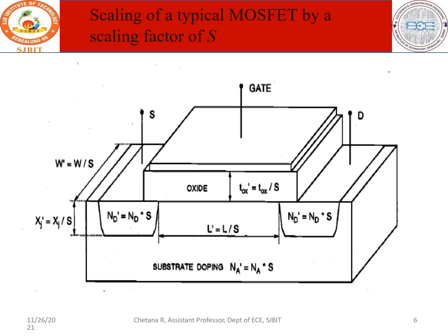Now how do we associate it with scaling? Whenever you are talking about doping, doping is normally indicated as Na, the ionic concentration of the doping. This has to be multiplied by S. These are the few things you have to remember. There is no choice. Please make a note of each and every statement I am talking. So the doping, Na, the concentration of the ion or impurities, has to be multiplied by S.